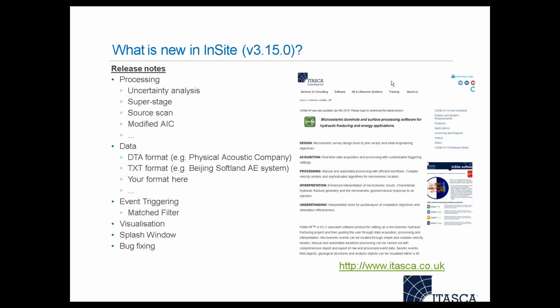Sorry about that. So we now support a new data format, the DTA format. That's for lab acoustic emission. If you have, for example, Physical Acoustics company hardware for data acquisition, you may encounter this data format, DTA. And now InSite can directly import a DTA format. Some other acquisition systems may use a TXT format. So if you're using that AE system, InSite directly supports that. And as always, we are looking for new binary formats. If you have a binary data format and you want InSite to support that, tell us the data structure and we'll add that to InSite free of charge.